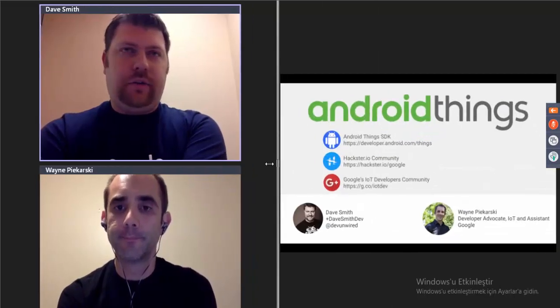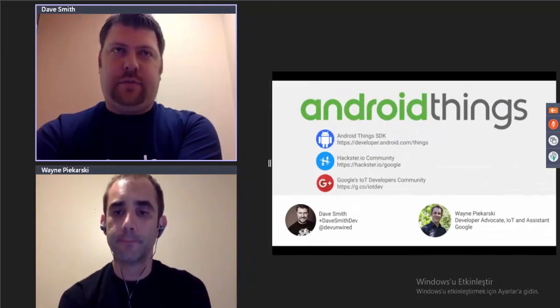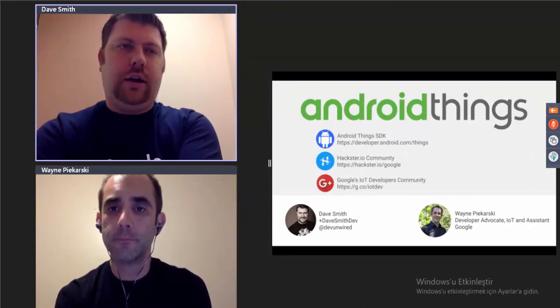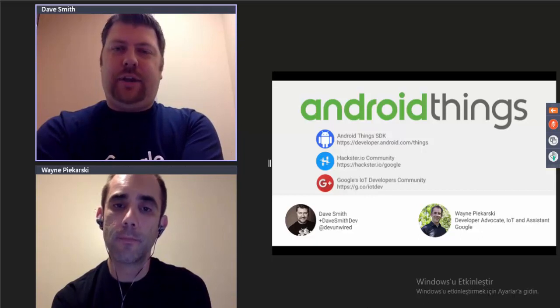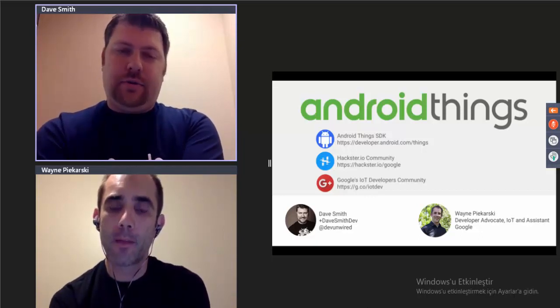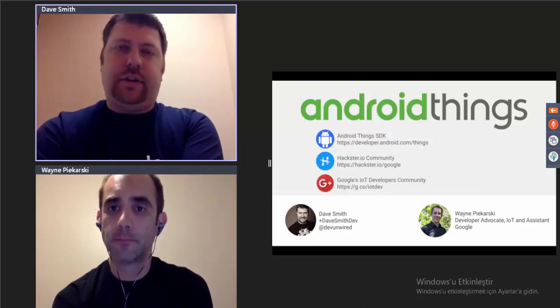Yeah, and the other thing that I would say there is if it is, in fact, only for development purposes, many of the developer kits do support displays. For instance, the Raspberry Pi has HDMI, you can plug in a display, or even the NXP kits have display connectors that you could connect a small LCD to as well. So if you just want to have a display while you're doing development, then maybe you don't pin that out on your product. That's perfectly fine.